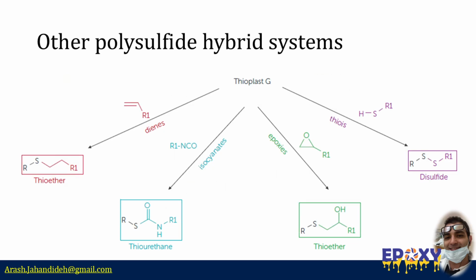Commercial two-component sealant formulations typically include liquid polysulfides blended with pigments, fillers such as silica and calcium carbonates, plasticizers, and various additives like adhesion promoters and antioxidants. The curing agent is prepared as a carefully mixed or milled paste composed of plasticizers, fillers, and catalysts to ensure consistent performance.